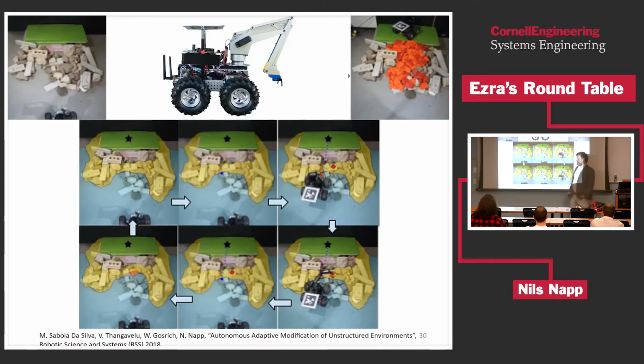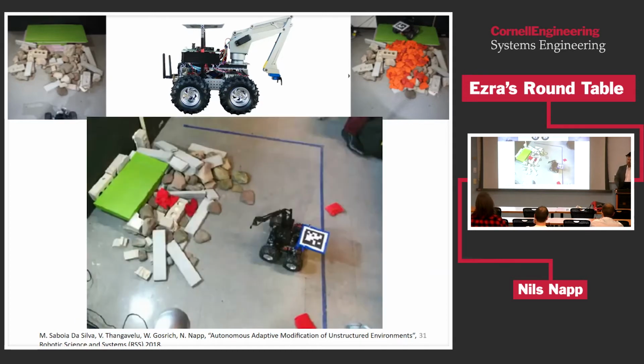Similar to the backing up step in the simplified 1D example, it's entirely possible that not all depositions will increase the overall navigability, because sometimes I put something up and then I made a cliff from another direction and stuff becomes non-navigable. But by repeating this process, I can also show that as long as everything is connected and I can find a path to these areas, the robot will succeed.